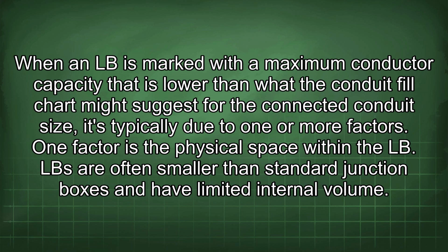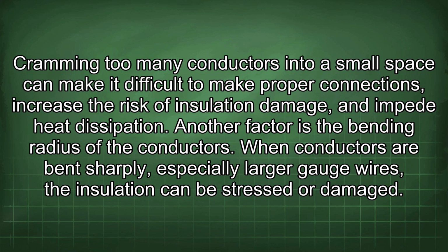One factor is the physical space within the LB. LBs are often smaller than standard junction boxes and have limited internal volume. Cramming too many conductors into a small space can make it difficult to make proper connections, increase the risk of insulation damage, and impede heat dissipation.